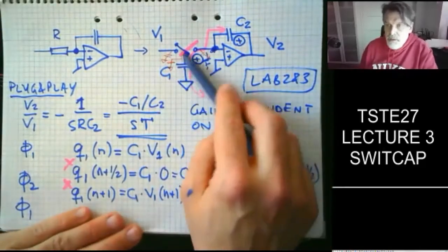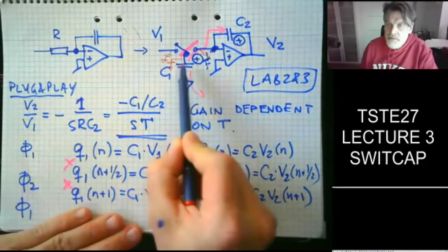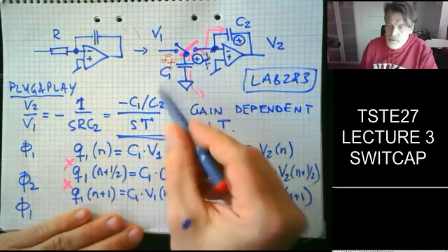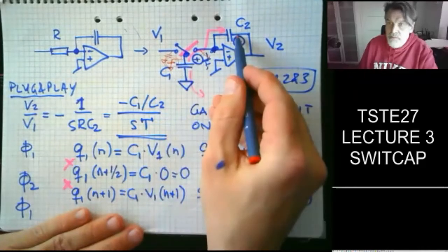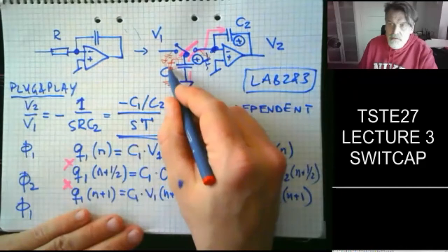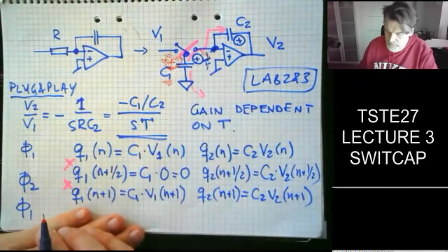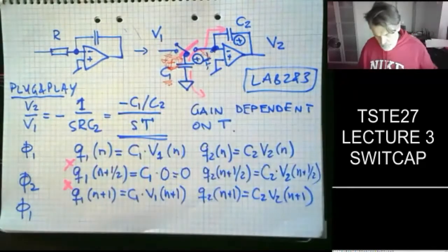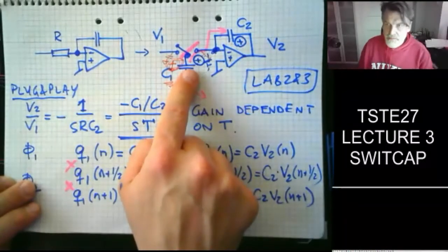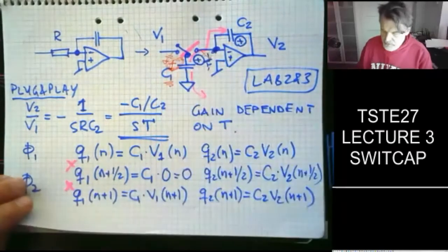Because what's going to happen is I'm going to charge this parasitic capacitance, which is associated with a plate here, and then during the next phase, I'm going to move the charge which was stored on these parasitic capacitances to the output. So even though I think I implement the C1, I will get this additional garbage, more or less, that will influence my transfer function. So this is a parasitic sensitive circuit because it has potential capacitors here that influence my transfer function.